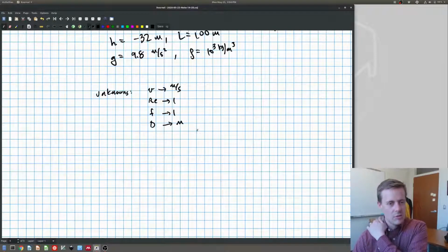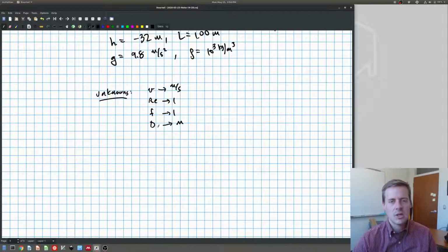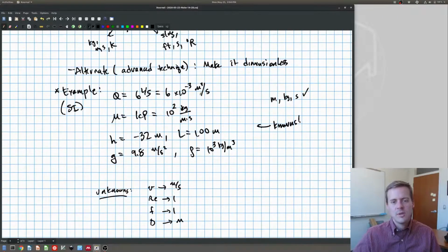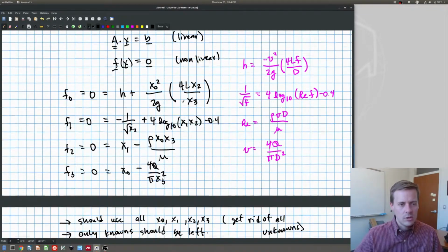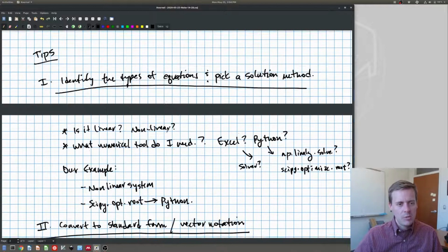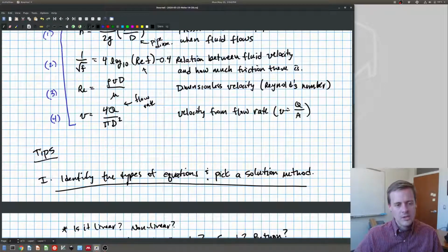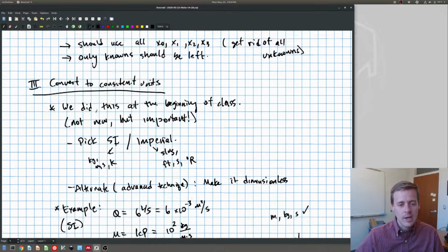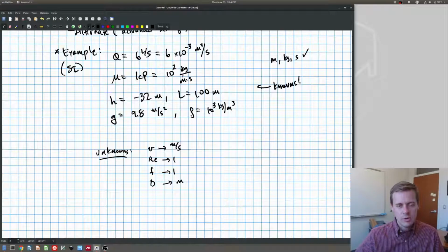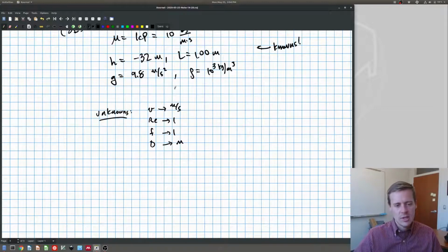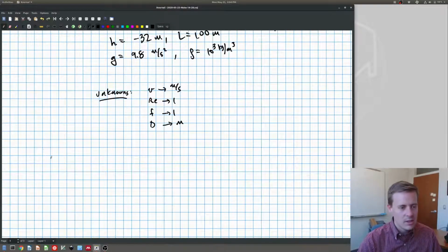All right, so I didn't have to do this. This is just going to come out because I'm sticking with these units. I don't even have to think about it or do the calculation. If I wanted to, I could come back up to my equation all the way up here and calculate what the velocity is, given this is meters cubed per second, and this is in meters squared, and that's going to tell me that's meters per second. And I can go through and double check and make sure all that's good. But the nice thing about once I convert this is now I'm ready to plug them in in the units that they go in as, and off we go. Okay? All right. So then the last thing here will be tip 4, which is make smart guesses.